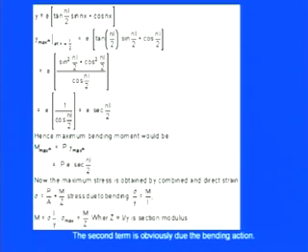Or we can say that now, since we know the y maximum, which is exactly at the center point of the strut, we can simply substitute this value, and the maximum bending moment in that case is P into e into sec of nL by 2. So now the maximum stress can be easily obtained by combining this with the direct stress.